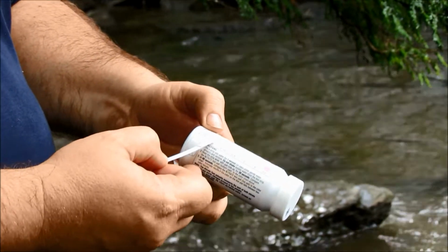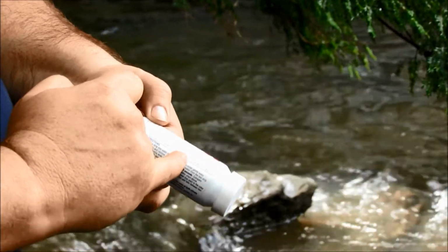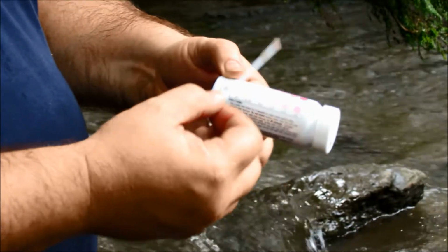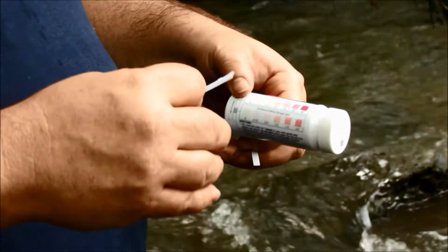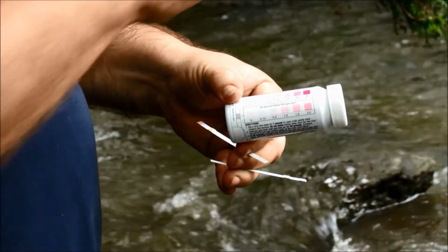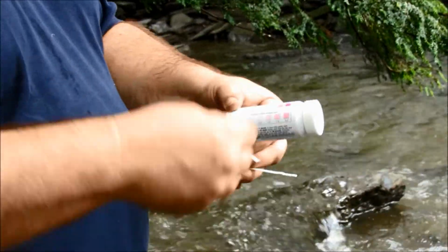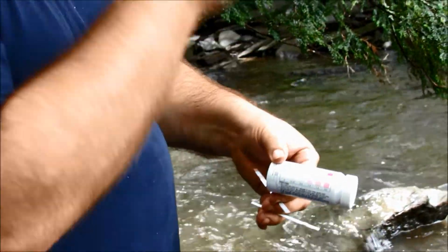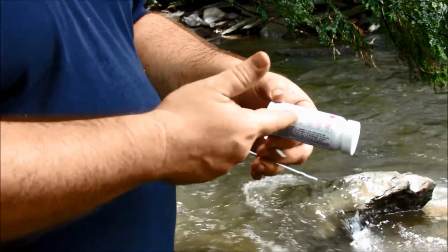For nitrite, NO2, the one down here, the drinking water standard is 1. So if you're above 1, it's an issue. That's a really nice, inexpensive thing that does really nice work to educate the community. Also, if you're doing a stream assessment and you're looking for an erosion problem or a nutrient problem, a big number or high conductivity is the place to do sampling. So if you're trying to develop a sampling plan, this would be really helpful.